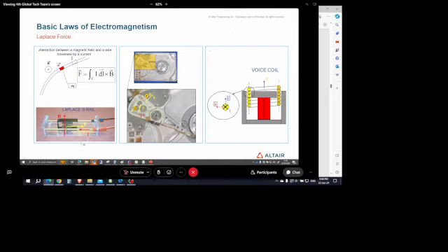What does it mean here? It means that the Laplace force will depend on the orientation of the current I am going to inject. If I inject it from the other side, the bar will move in the opposite direction, not like the magnetic force actually. So the principle of the Laplace force is that when a given conductor is inside a magnetic field and current is applied, a Laplace force will appear on it. And this Laplace force orientation will depend on the current orientation.